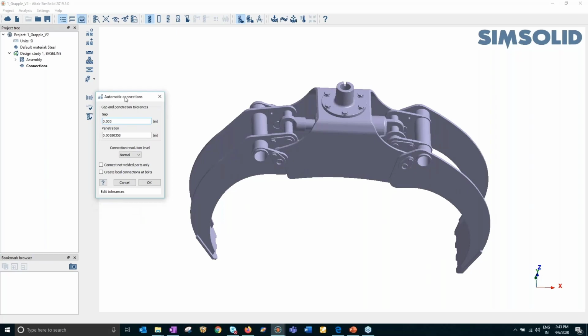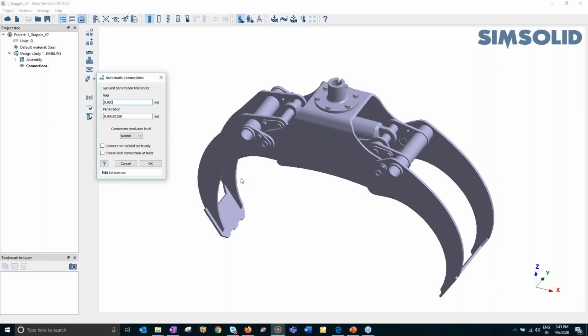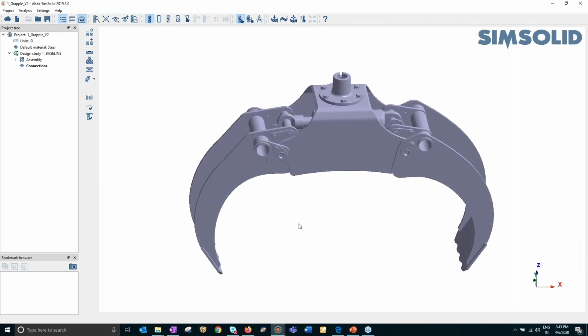it will pop up with an automatic connection creation window. Now, since this is a web-based training, I'll go a little bit deeper in detail on each of those icons as much as possible, although I'll restrict myself not to go too deep so that we can save some time. What this does is it helps you create connections automatically as soon as you import a geometry, but that is not compulsory. You can safely cancel this and decide to do something else as well.